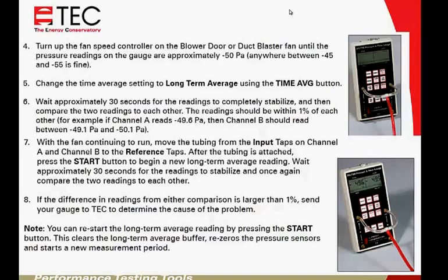So a lot of times I'll just start them out in pressure mode, and then walk them through, actually have them pull out their blower door manual and go old school with them and say, all right, we're going to do this old school where you're just going to use the gauge in pressure mode and get a fan pressure and go to the chart and find out what pressure is on the chart, and follow it across to what ring is on, and really have them understand that the DG-700 is, what am I really measuring?